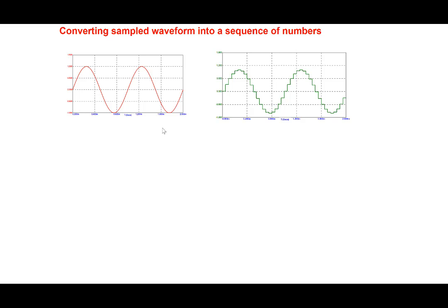We would now like to convert it into a two-digit decimal number, okay? That particular process is what is called quantization. Right now, after sampling and hold, we still have an analog value, and this value could be anything between 0 and, let's say, 2 volts. Now we would like to quantize it, so we would like to convert it into two discrete decimal values.